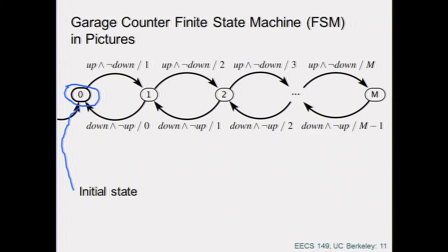Now, if I don't give you the initial information, can you say what happens to the system? Big question mark. Can I? Or am I stuck? Is it essential to give an initial condition? Yes, right? It is absolutely essential. Because remember that the state is information about what happened in the past. So if I don't tell you what happened in the past, where the heck do I know where I am? Right? So you must always give an initial condition. Now, mathematically, if you have x dot equal to f of x, you cannot solve a differential equation unless you have an initial condition.